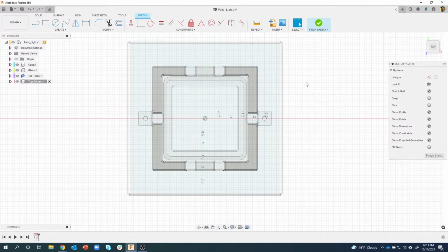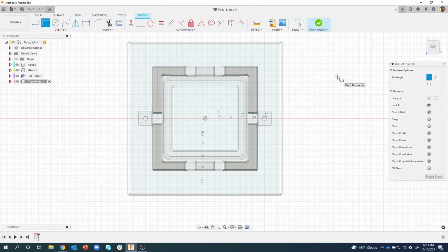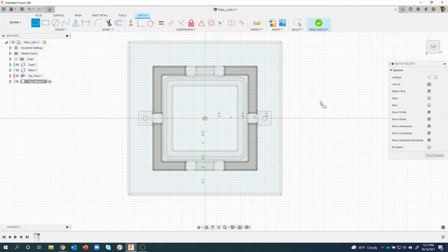Okay? Well, all I have to do is right click, drag down. Oops, I'm trying to do it slowly. I'm going to right click, drag down, and go to 2 o'clock, and there's my rectangle command. If I right click and go to like 10 o'clock, there's my circle command. If I just right click and drag straight down, there's my line command. So what is it doing? It's basically going here, into here, and then to 2 o'clock, or to 10 o'clock, etc.